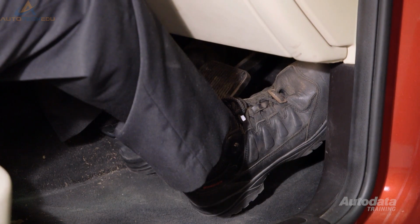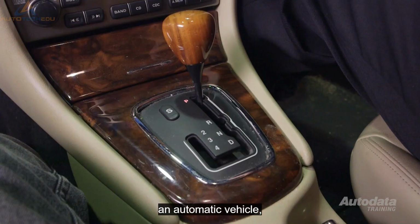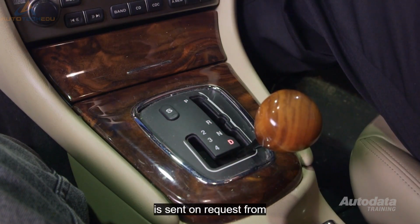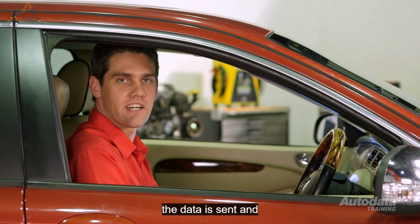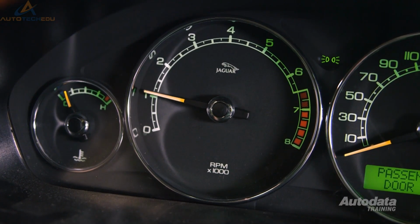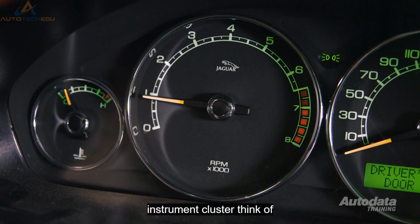For example, if I press the brake pedal or select drive in an automatic vehicle, this is known as an event, and the data is sent on request from the corresponding control unit. Periodically is essentially real time, where the data is sent and constantly adjusted. For example, the TPS or the tacho reading in the instrument cluster.